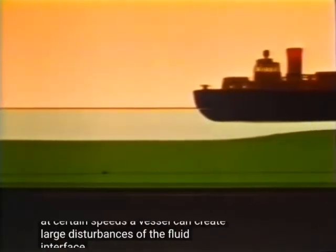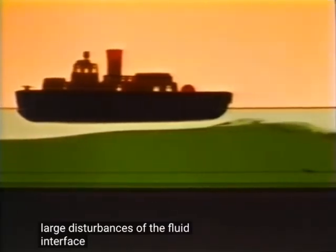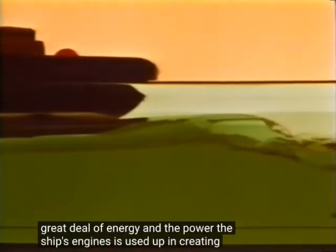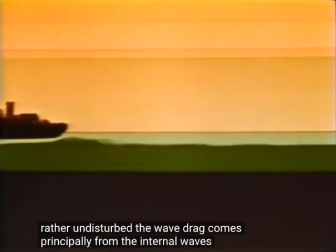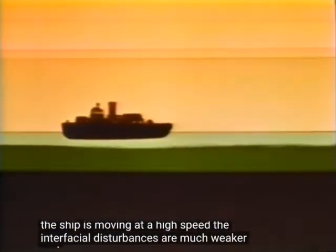At certain speeds, a vessel can create large disturbances at the fluid interface. These disturbances contain a great deal of energy, and the power of the ship's engines is used up in creating them. Notice that the liquid air surface is rather undisturbed. The wave drag comes principally from the internal waves. If the ship is moving at a high speed, the interfacial disturbances are much weaker, and the deadwater phenomenon no longer exists.